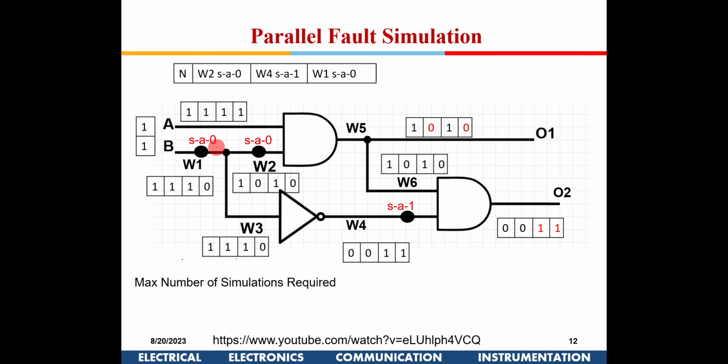Now similarly, this net is coming here, so this 1 1 0 comes as it is. Now there is an inverter, so all these get inverted. So 1 becomes 0, and it should have been 0 0 0 1. But the third one, if you see here, is stuck at 1 actually, W4. If that fault is there, then it is stuck at 1 here, so this has changed to 1. You need to make sure all the registers get updated accordingly.